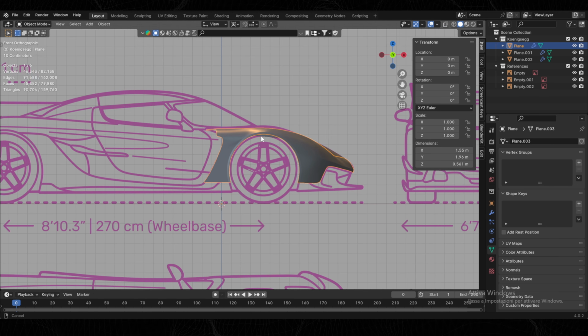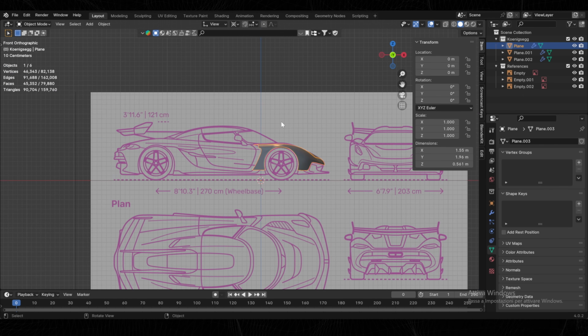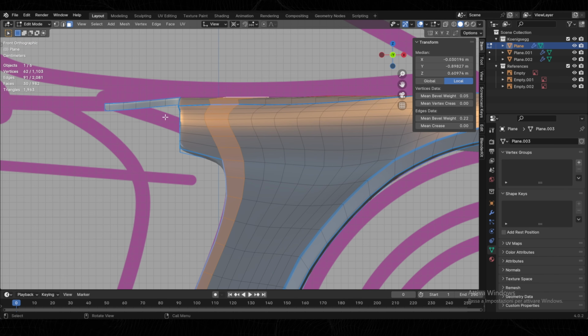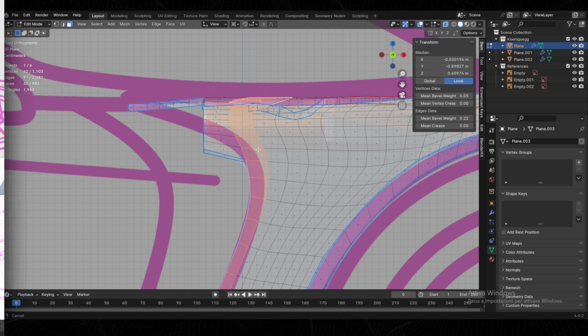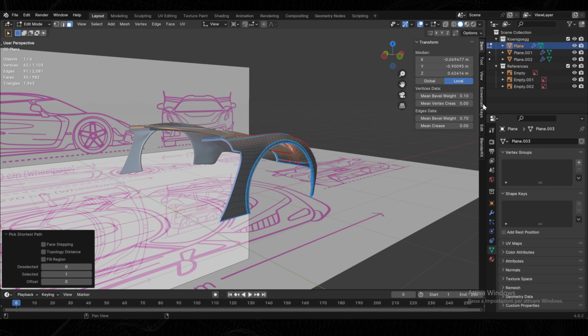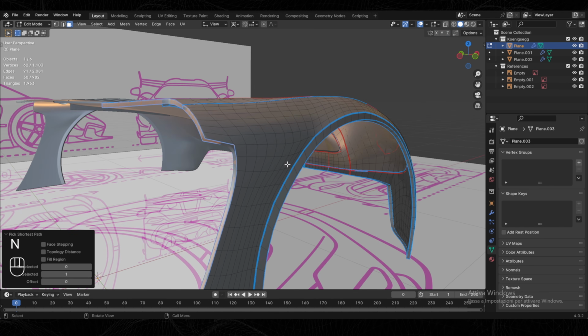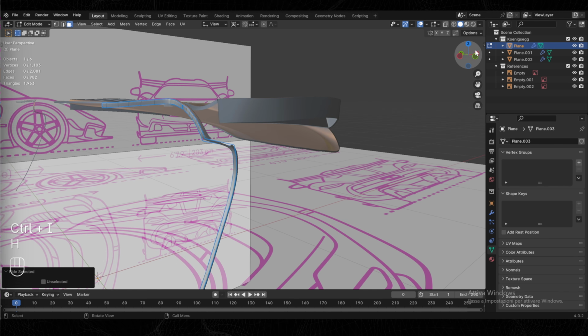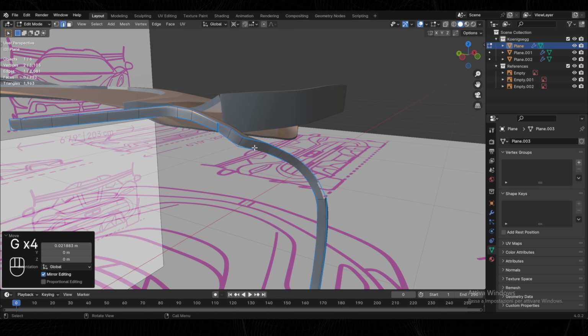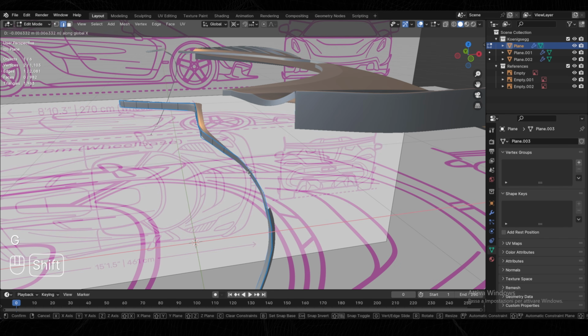Before starting to model the doors, we'll firstly have to adjust the shape of the hood we modeled in the last part, since I kind of messed it up. The first thing I did was selecting these faces on the hood's edge. Then I isolated them with Ctrl+I+H. Then I simply messed around with these edges, switching from side to top view to align them correctly.